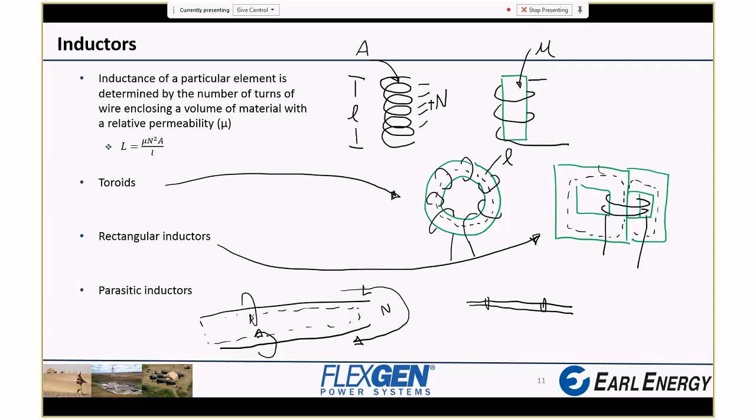And that can affect our circuits pretty significantly if you have wires running feet apart for hundreds of feet across the lab. It's going to amount to a significant inductance. It's also a great way to pick up noise, because just like wires spread apart can generate a pretty nasty magnetic field between them, they're also sensitive to magnetic fields passing between them.